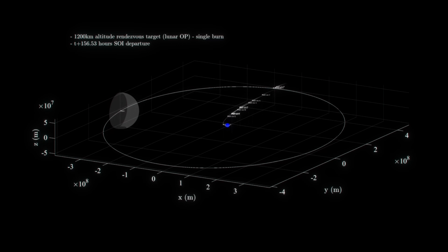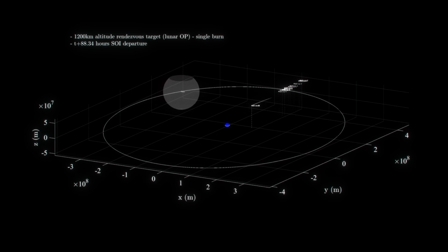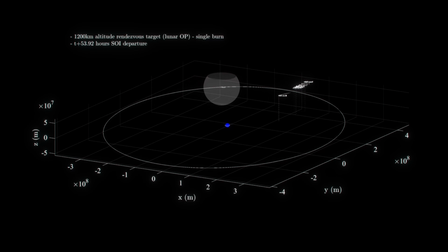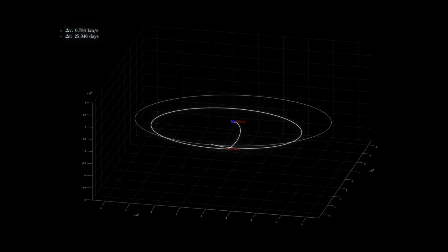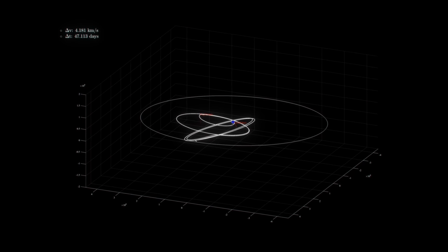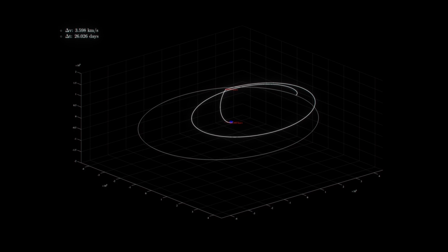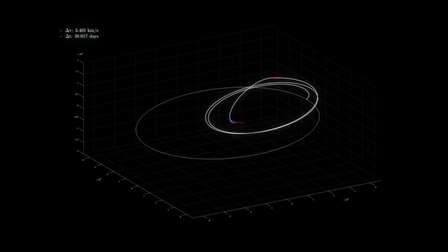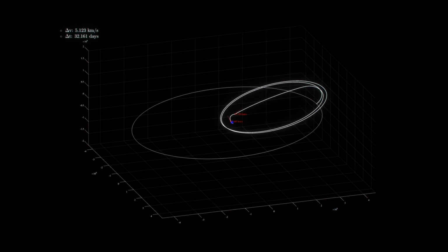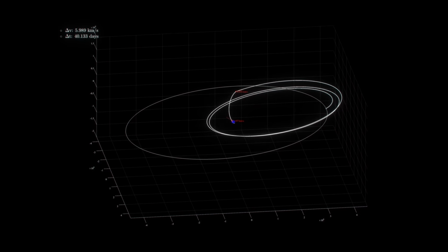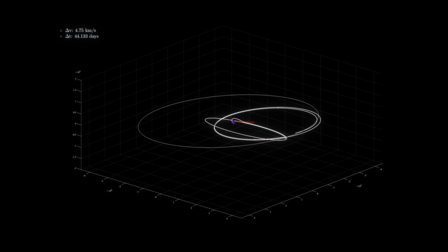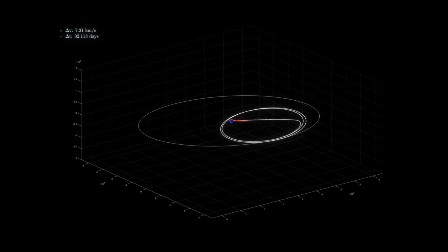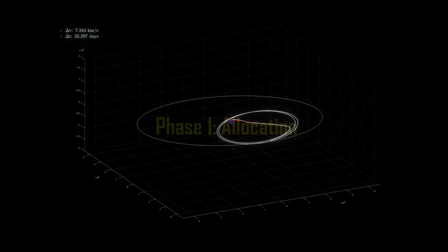In the last video, we worked backwards using patched conics to find what looked like the best lunar launch location. And honestly, if all we had done was upgrade from patched conics to a more realistic multi-body simulation, the old location might have been good enough. It probably would have shifted somewhat, but not necessarily enough to throw the whole thing out. But we didn't just upgrade the physics, we also introduced multi-burn trajectories, which is a much bigger deal as that new degree of freedom changes the design space completely. So we had to re-find the starting location from scratch.